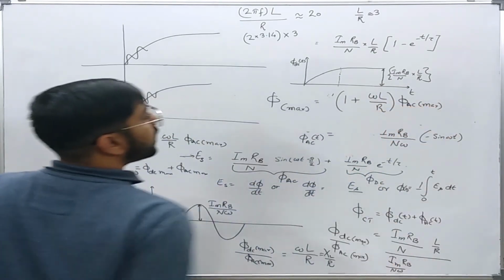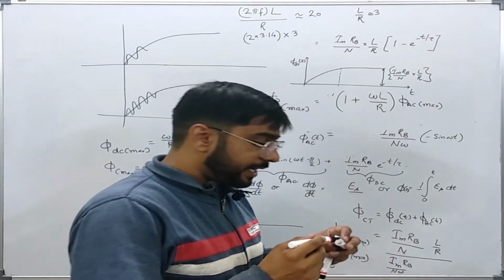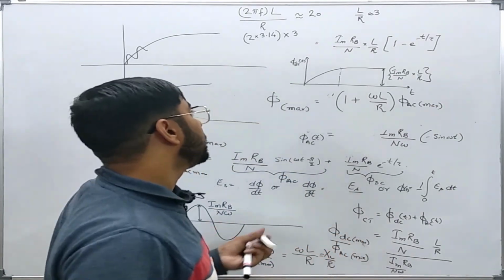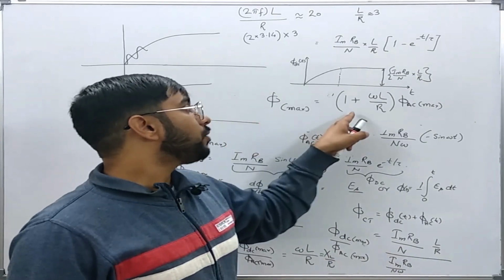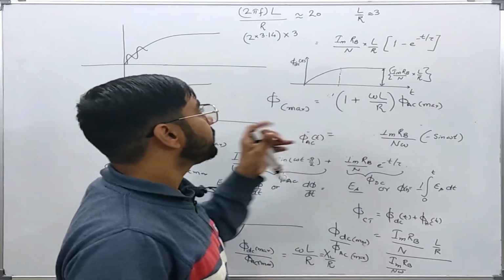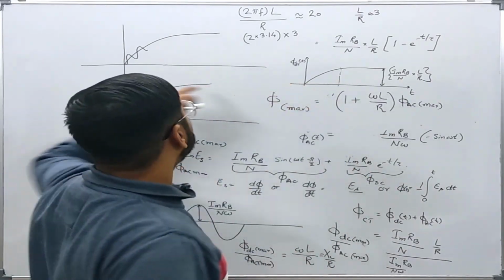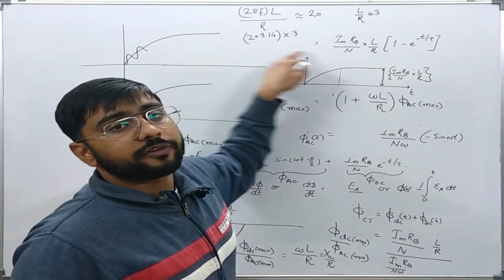So you see that during the transient, the core of the CT may have to carry a flux which is more than 20 times the steady state flux, or just the flux that should be there when this DC transient part is not available.